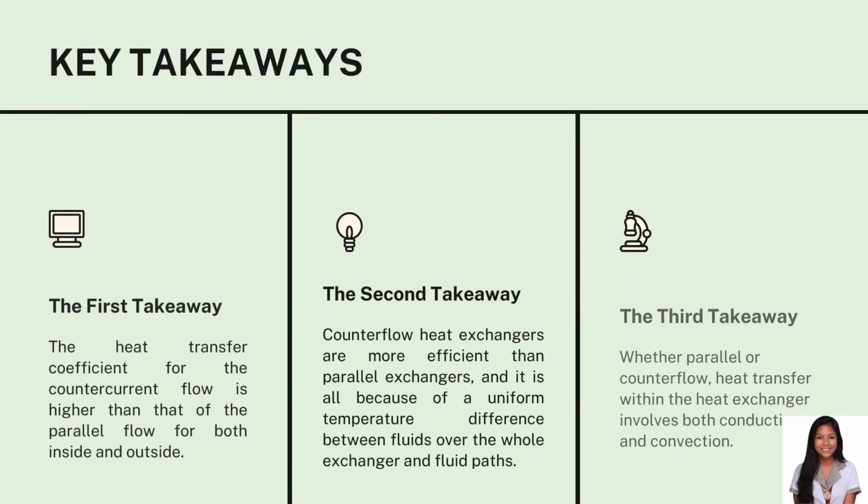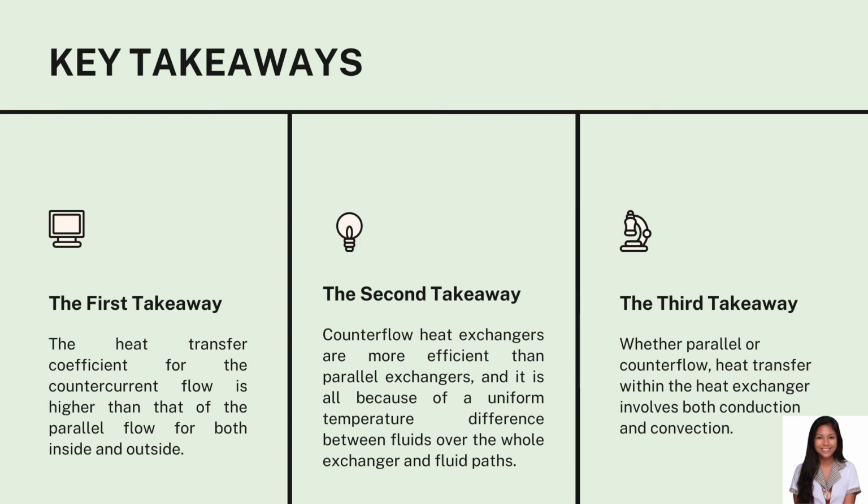To simplify the things I have said, the counter current flow heat exchanger has its log mean temperature difference value greater than that of a parallel flow heat exchanger, and therefore for achieving the same degree of heat transfer, the heat transfer area requirements are less in the case of a counterflow heat exchanger. This area saving is the biggest advantage of the counterflow heat exchanger over the co-current or the parallel flow heat exchanger. Now, as far as the advantages of the parallel flow heat exchanger are concerned, the parallel flow in heat exchangers minimizes the chance of freezing or channeling.